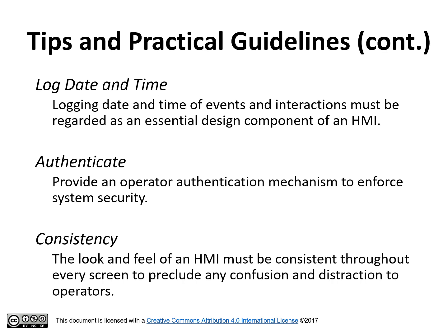Consistency. The look and feel of an HMI must be consistent throughout every screen to preclude any confusion and distraction to the operators. An exit button that is depicted 2 or more different ways can also create confusion to any user.